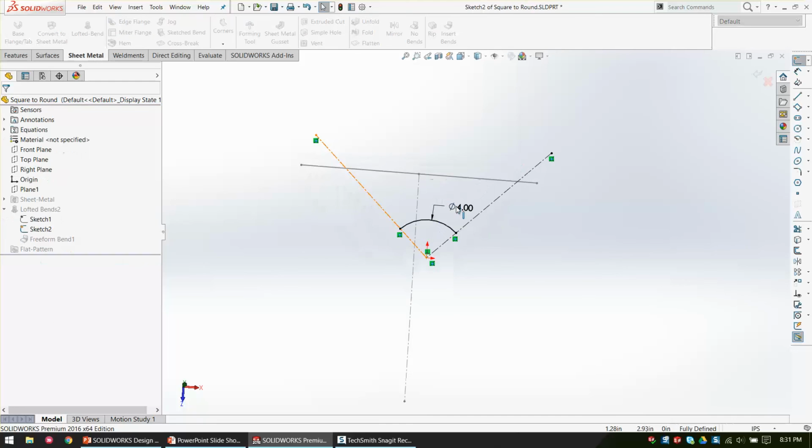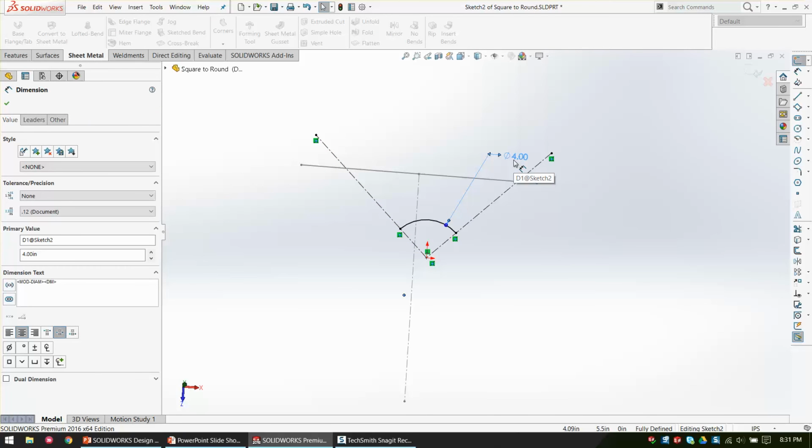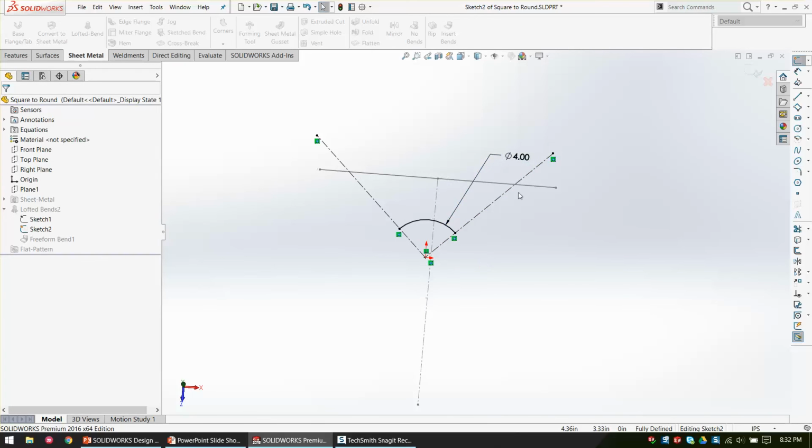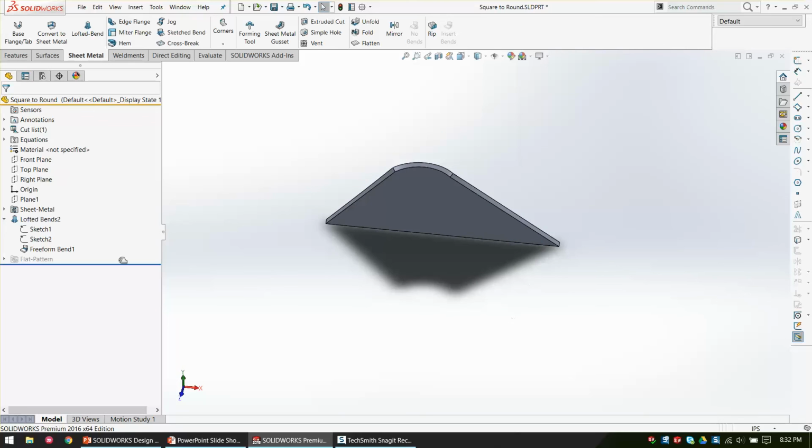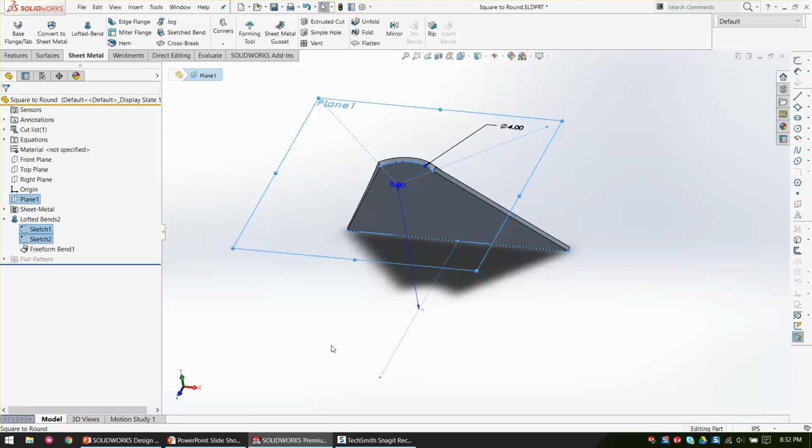And same thing here. Single dimension, and again, what's important to me is diameter. So I'm going to put a diameter dimension on here, not a radius, because I don't want to do math. And I'm going to use the construction geometry tree. I don't have a 90 degree here. I'm not defining this with dimensions. I'm constraining it to the existing sketch, which then gives me a square. So this is literally 3 dimensions, plane offset, and 2 sketch dimensions, squared around. While you got your material thickness.